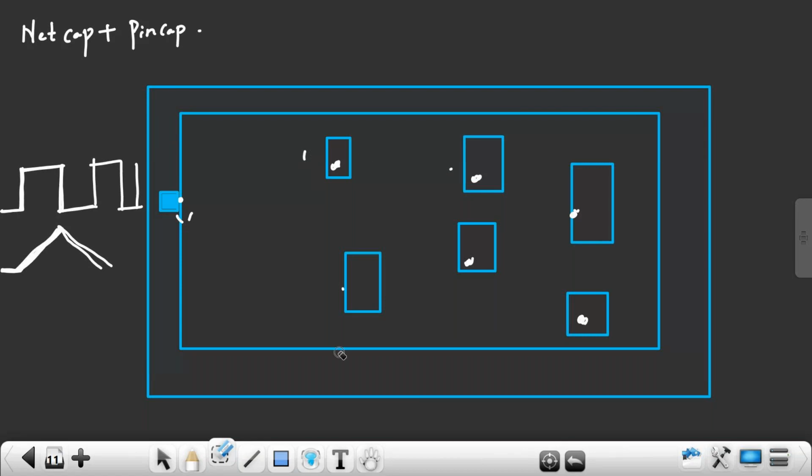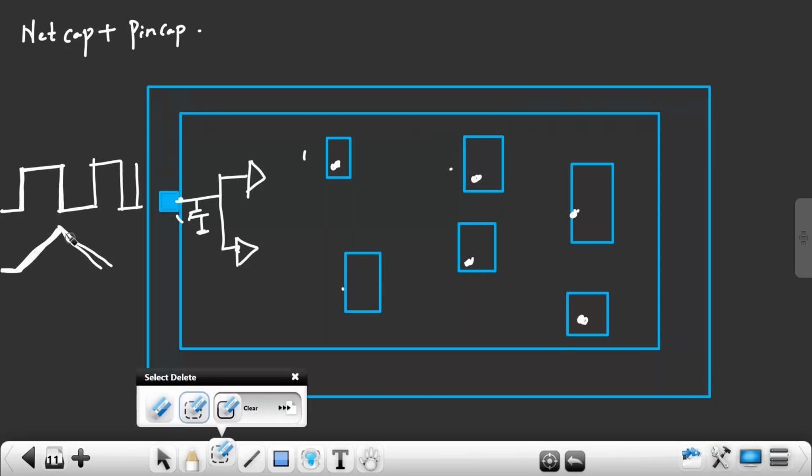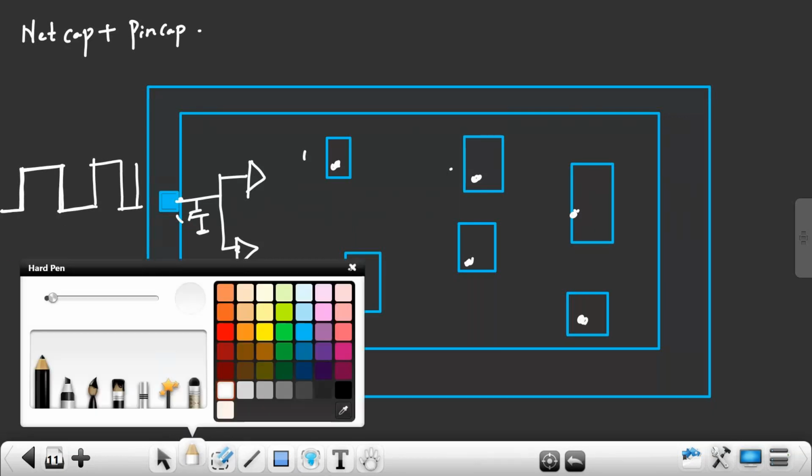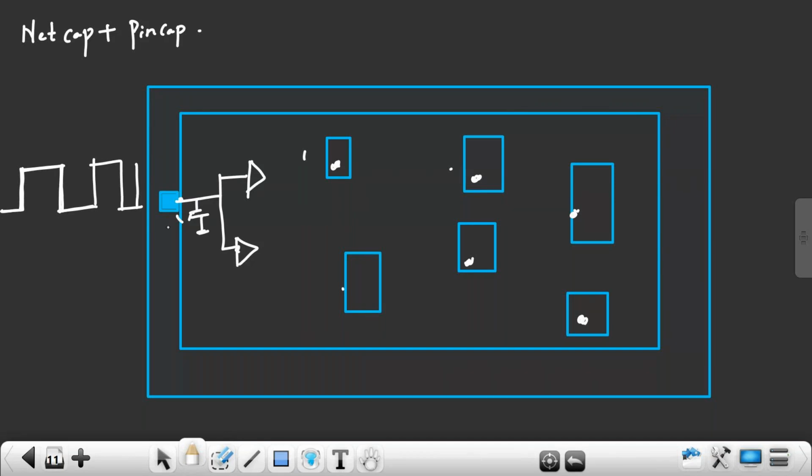What is a clock tree? For example, I want to connect these cells. First this port I will connect to only 2 buffers. Now what is the load on this port? The pin capacitance of this and the pin capacitance of this. Just 2 femtofarad, 1 femtofarad here, 1 femtofarad here. Then the rise time will reduce, because now I can easily charge my load capacitance and easily discharge it, because this value is very less.